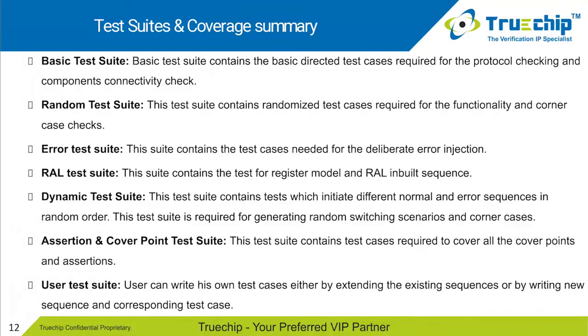Test suites and coverage summary. We have these types of test cases in our test suite: basic test cases, random test cases, error injection test cases, RAL based tests, dynamic test suites, assertion and cover point test cases. Users can create their own test cases using our sequences. They can extend and create their own sequences, and their own test cases also.